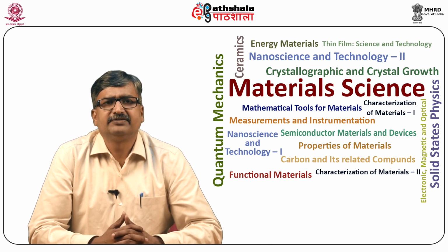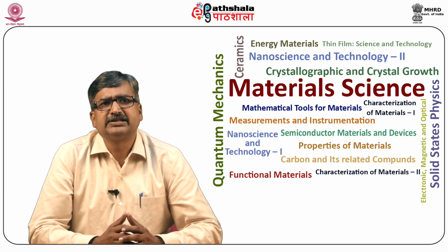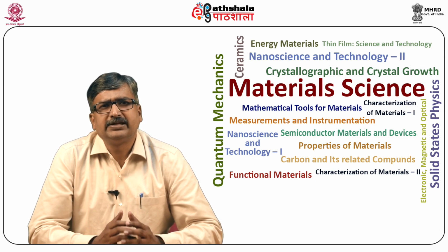A new design of nanowire graphene based solar cell has been shown in the figure. This new design consists of a layer of graphene, which is a transparent cathode, a conducting polymer, to maintain integrity, and a ZnO nanowire layer as electron transport. Lead selenide quantum dots, hole transport, and an Au layer as an anode.